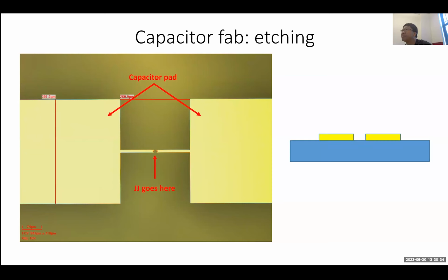So those areas will be masked by photoresist, right? So you wouldn't really expect your etchant or your etcher to actually interact with that region, but the interface between the substrate and the vacuum, so this area, for example, can be affected by your etching process.